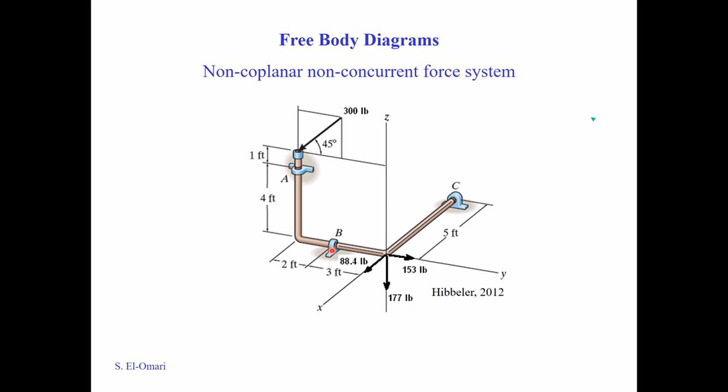If you look at that table for journal bearings, you will see that it has drawn two force reactions and two moments, but placing another type of support here, in that case the journal bearing, will cancel this moment rotation. So you also have to be very careful. This happens also to a hinge type of support. A hinge that you see in a door: if a door was supported with only one hinge, it would prevent motion along the three axes and rotation about two axes. But placing another hinge in the door will cancel this rotation effect, and you will have the hinge with only three force reactions.